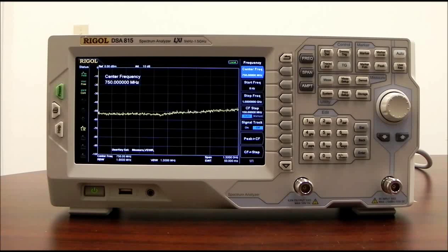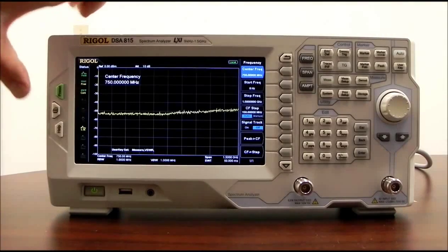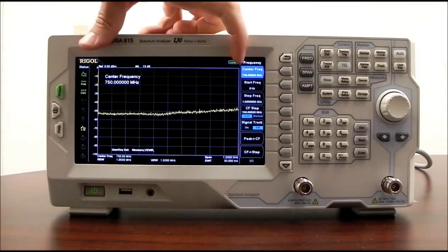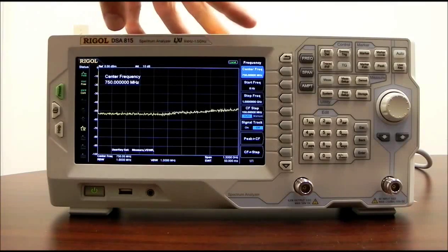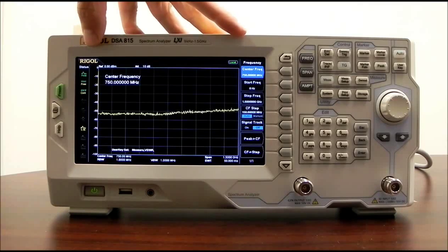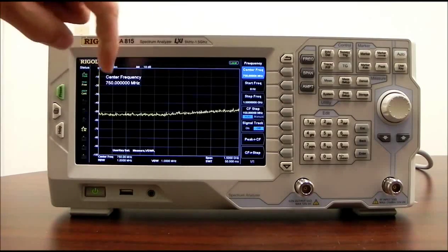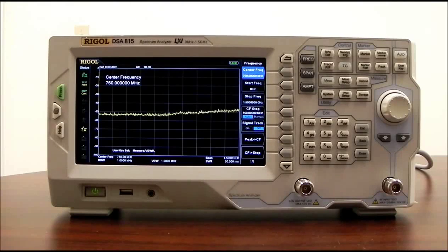Let's start out by going over a little bit about what spectrum analyzers are capable of, or what they are used for. Much like an oscilloscope, the spectrum analyzer is going to show amplitude, but instead of showing amplitude with respect to time as in an oscilloscope, it's actually going to show it with respect to frequency. And so what we can get is a very good indication of a frequency level and its amplitude relative to absolute value, but also relative to one another.